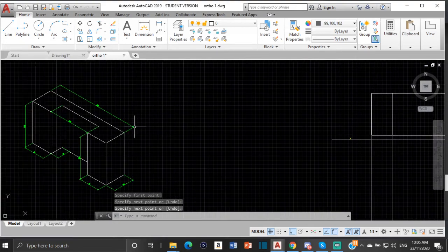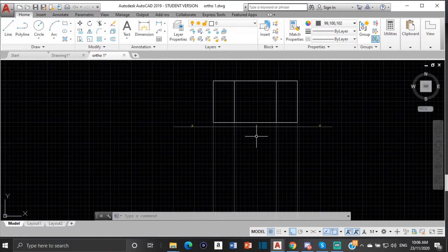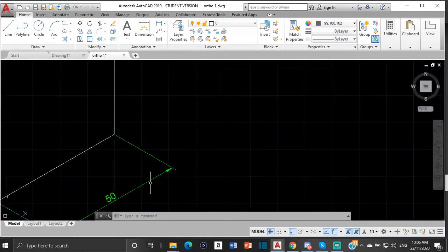Now, over here, this is the plan view. So this is what I'll see when I'm looking down. The first thing I need is this distance, the width of the plan view, because I already have the length. The length is from here to here, which is the same distance as from this line to that line, which we already brought down from the front elevation. So we already brought down that line and this line, so we know the length of the front. What we need now is the width, and it says here that the width is 50.